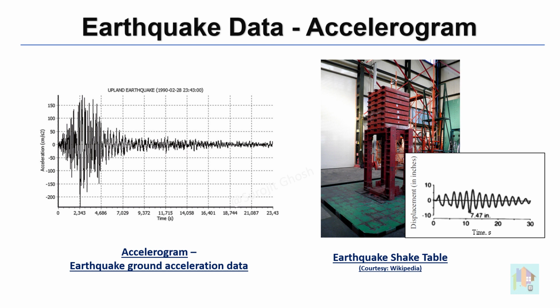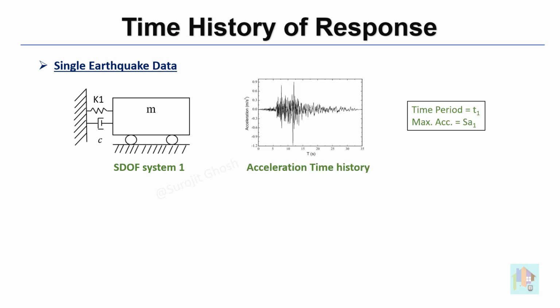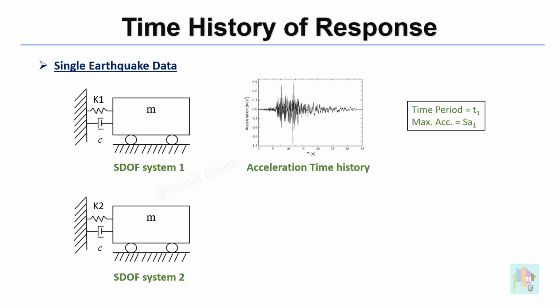This scaled model is known as the single degree of freedom system or SDOF. What is a SDOF system and how it is related to any real-life structure? That is a complex topic, and I am not going to discuss this today. This SDOF system has a specific stiffness and time period, and from this simulation, maximum structural response against that recorded ground shaking is recorded. Then same steps are repeated for another SDOF system with different stiffness. As fundamental time period depends on the stiffness, second system has a different time period.